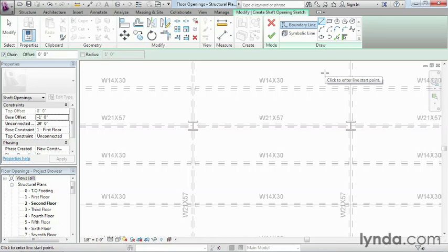Now I happen to know that this happens to start off about 1 foot off of where this beam is placed at. So in order to be able to do this, we'll start off by using the line work tool, but we're going to set an offset value to this line work tool. So when we start to draw, it's going to actually place this first line 1 foot away from where we're drawing the line at. So we'll select offset 1 foot, pick the beginning spot for where this line should be, and then move straight down.